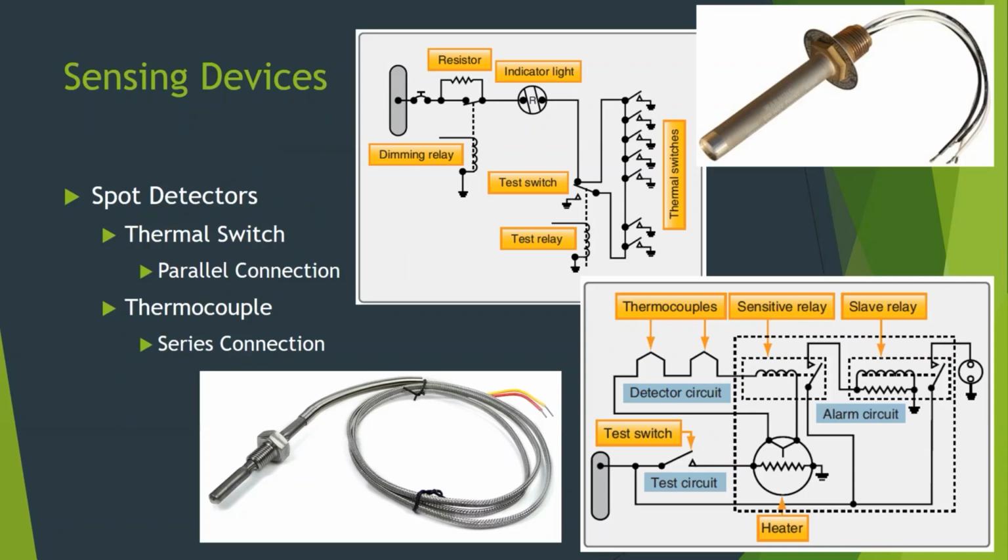Because it's become really cheap to monitor a bunch of switches using a computer, basically. Why do that rather than having them all in parallel like that? Where does that make your job easier? What's that? You're on the right track. Who said troubleshooting? Troubleshooting. So the older planes I worked on were set up like this.